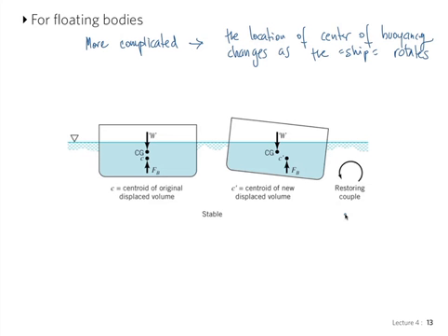It's much more complicated than the usual rule that you're told, that if the center of gravity is below the center of buoyancy, the thing will be stable, and if the center of gravity is above, the thing will be unstable. That only applies for completely submerged bodies, so it's okay if you're a submarine, but for everything else, it's much more complicated. And this can be very difficult, and it's quite an elaborate engineering activity to actually look at the stability of cargo ships and so on.